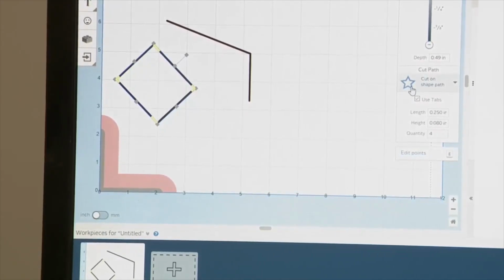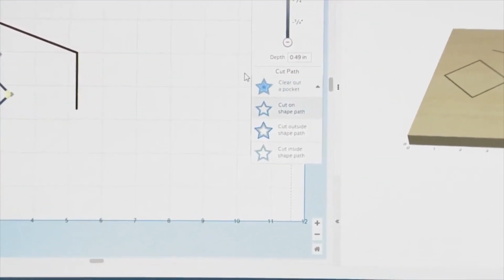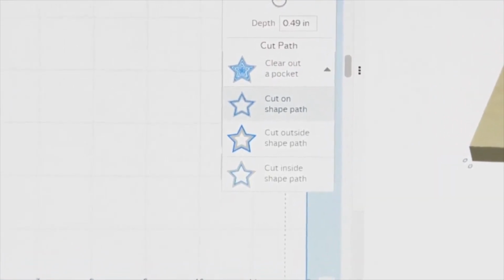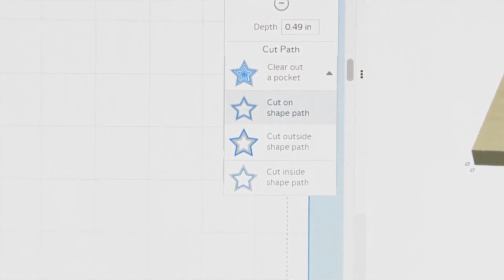and using a cut path that cuts the square out, we wouldn't want the inside of the material to fall out. Moving back to that cut path tool I showed you, the square right now is set to just have the router cut the perimeter, leaving a finished square on the inside and a finished piece on the outside that can be lifted out.